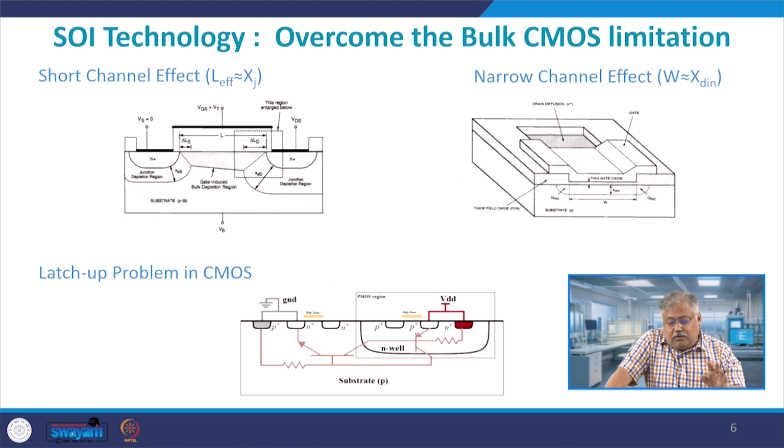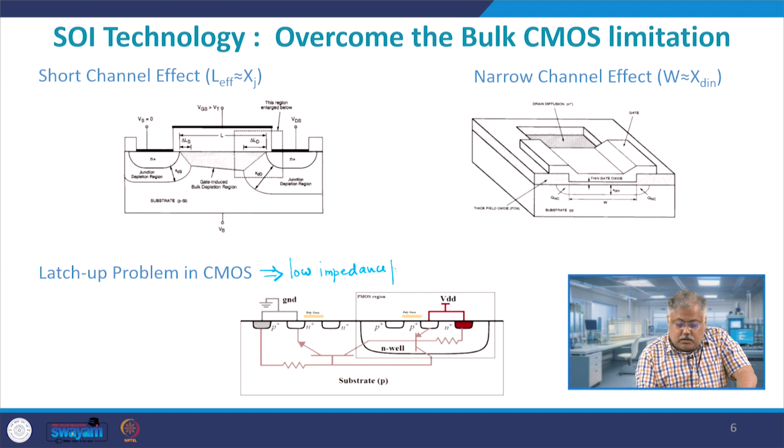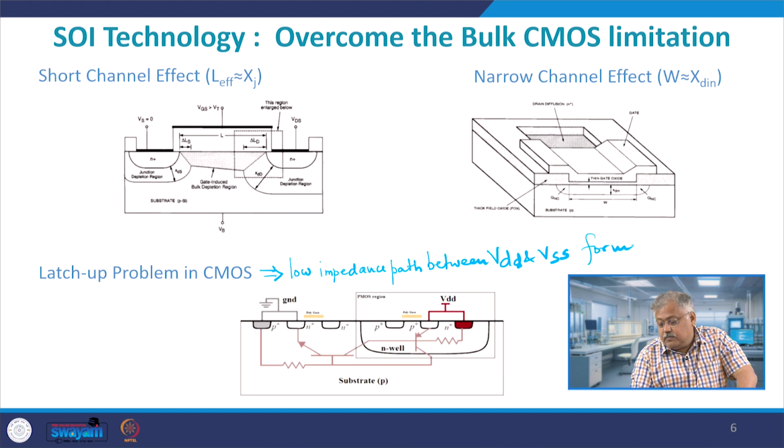Now, let us look at one advantage of SOI devices, which is what is known as the latch-up effect. Basically, what is latch-up? Latch-up is nothing but a low impedance path between VDD and VSS, because of the formation of PNP and NPN transistors.